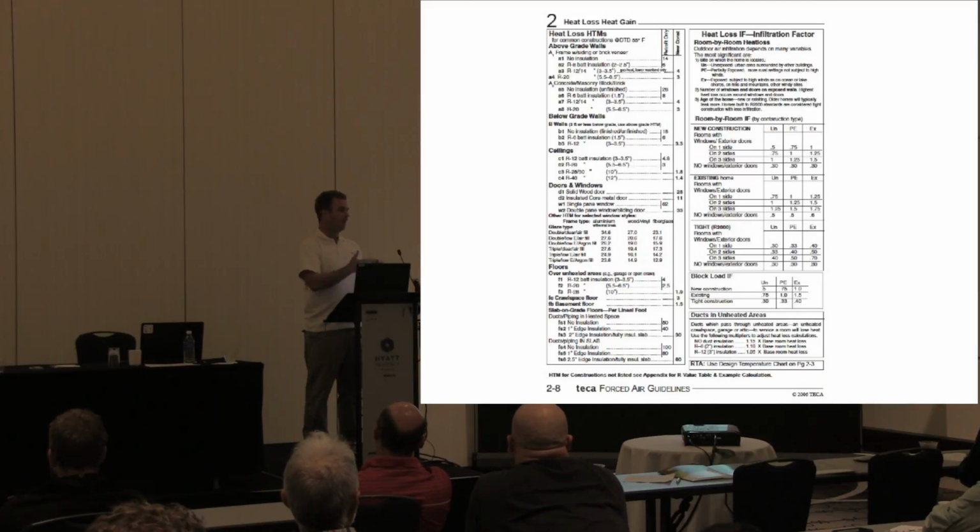So the way I always remind it, and I have apprentices that I make do this so they understand what we're doing. I just make them sit in the office for a while. The thing to remember is anything exposed outside, you have to remember ceilings, walls. If you have floors that are exposed, like a carport or an overhang or something like that, make sure you're including those things. And then we still have loss through the floor because the ground, even in a basement, is 50 degrees Fahrenheit. So we want to make sure that you're still going to have heat loss.